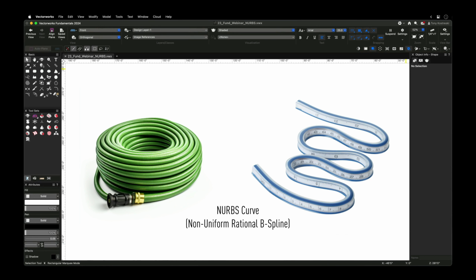First, NURBS curves are mathematical representations of smooth, continuous curves. I want you to think about garden hoses or flexible rulers if you've ever used one. You can bend it into any shape you want, but it will always be smooth and continuous. They are made up of a series of control points, and you can move those control points to change the shape of the curve. We'll dive into that in just a moment.